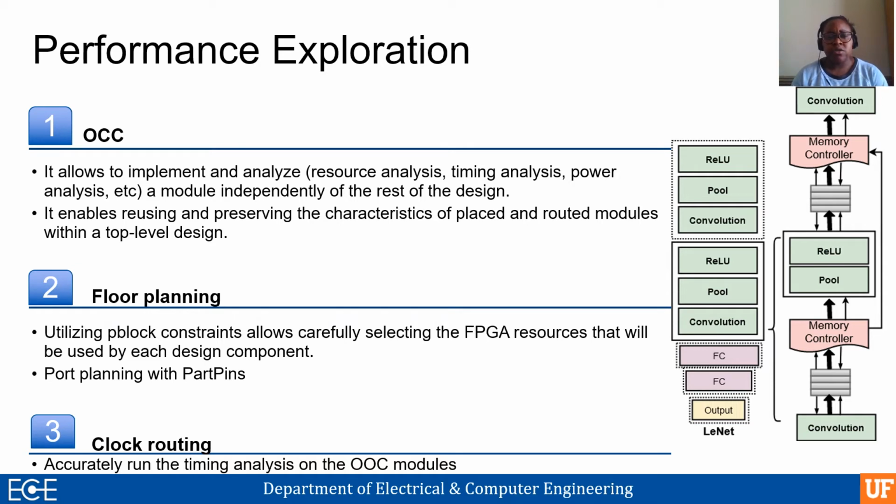This allows us to implement and analyze the model independently from the rest of the design. It also allows us not to add buffers to the I/O. Another advantage of synthesizing the component out of context is that it enables us to reuse and preserve the characteristics of placed and routed modules within the top design.